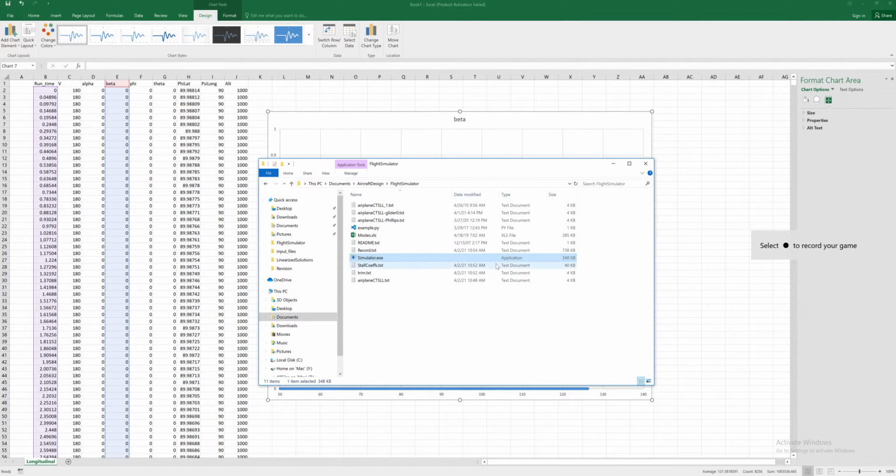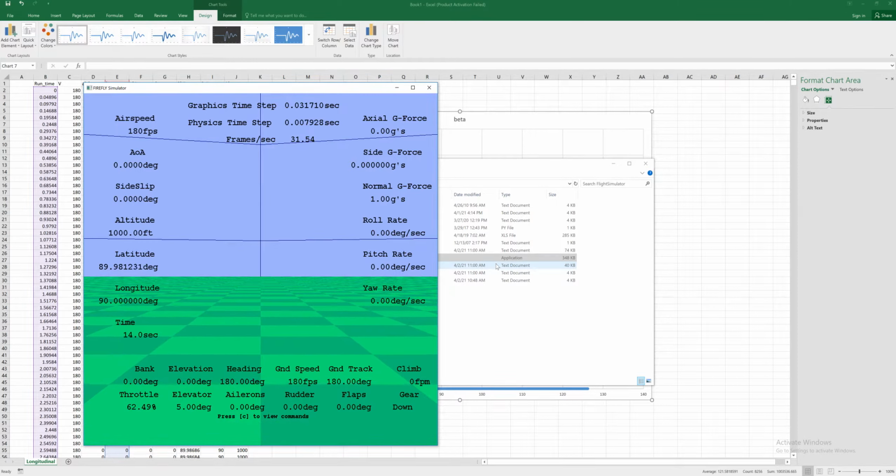Okay, so we're going to restart the sim, and this time we're going to look at each of these modes a little differently, but let's do what's called a rudder wrap. In this case, the pilot would just kick one of the rudder pedals really quickly and then take his feet back off them. And so I'm just going to try to simulate that by doing a quick rudder input and release.